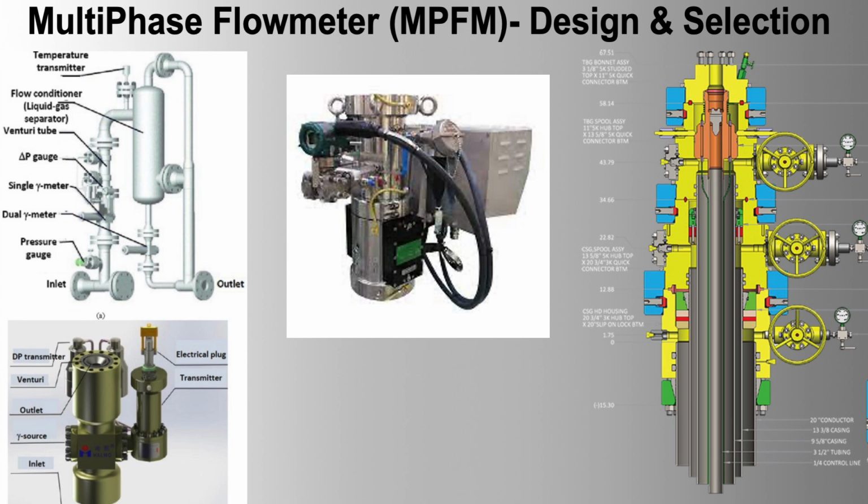1. Integration with flow meter. Automated control, use MOVs for automated control of flow paths based on flow meter data. Feedback loops, real-time adjustments to flow rates based on flow meter measurements. 2. Operational efficiency. Remote operation, MOVs can be controlled remotely, reducing the need for manual intervention. Safety, enhanced safety by minimizing personnel exposure to hazardous environments. 3. Maintenance. Diagnostics, MOVs with self-diagnostic capabilities to identify and report issues. Redundancy, implement redundancy in critical applications to ensure continuous operation.